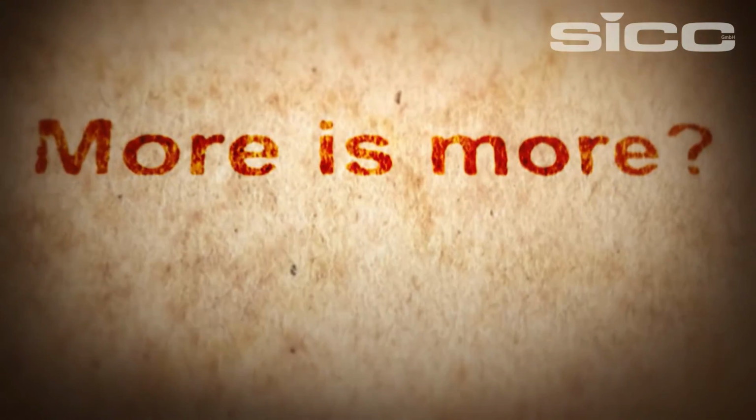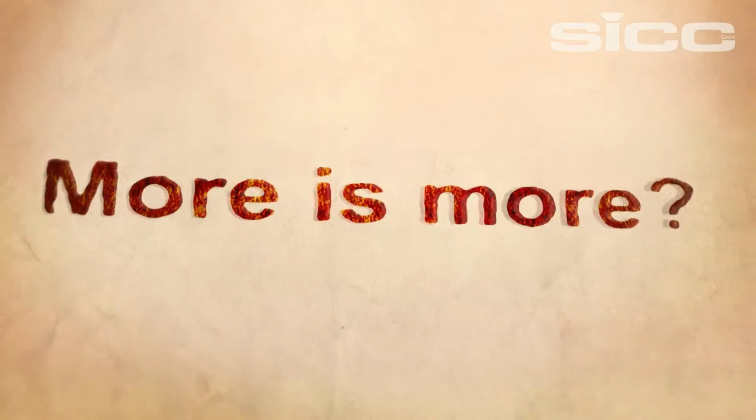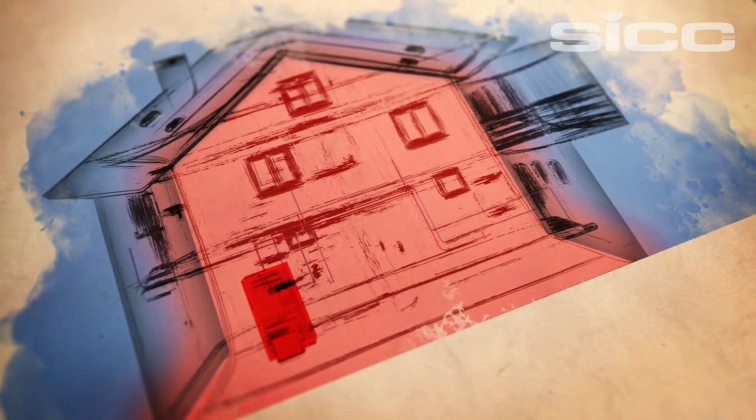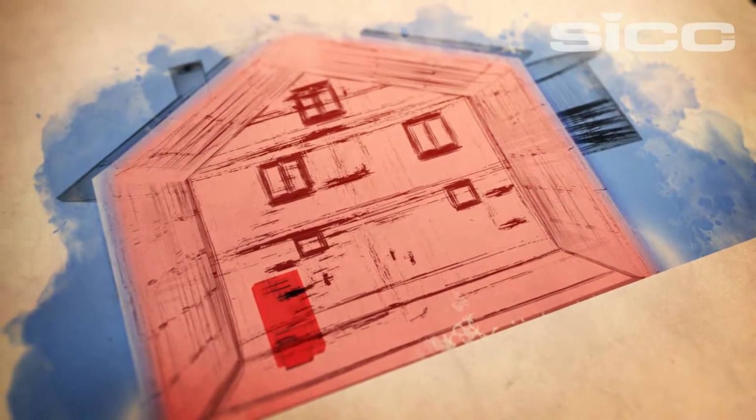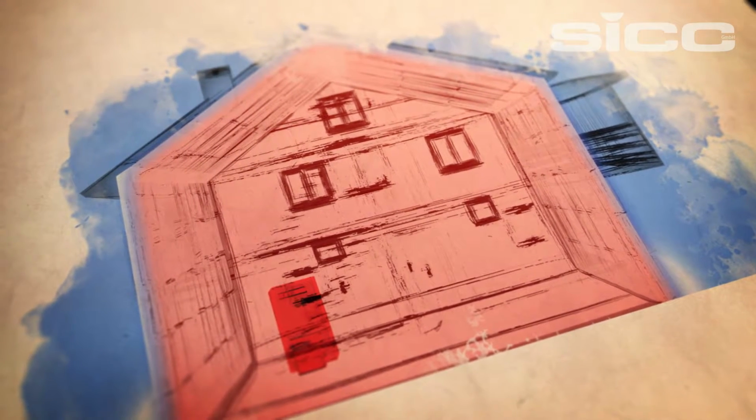So in order to get the lowest U-values, the heat resistance of the shell has to be improved. Subsequently, the energy consumption falls. This may happen when an additional layer of insulation is added to the existing facade, or if during construction, building materials are used that offer better insulation value.